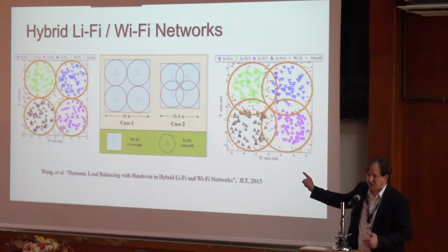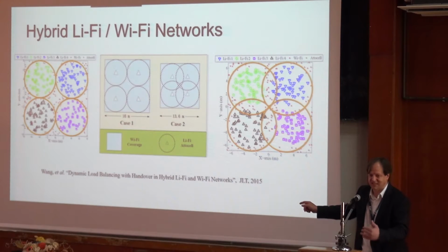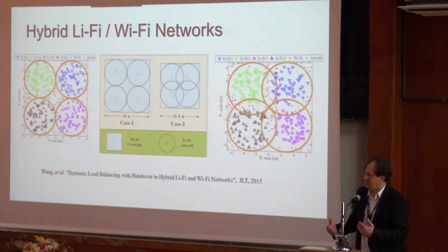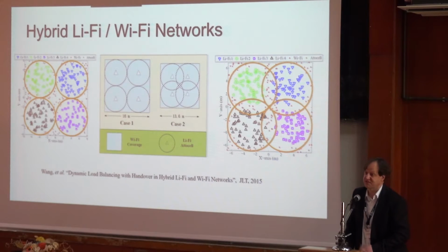We've then developed a simple load balancing algorithm that is based on the signal to interference plus noise ratio, SINR. Whenever the SINR of Wi-Fi is higher than the SINR of LiFi, the user will be served by Wi-Fi. That's why you see red dots in the interference regions. That means that users are covered by Wi-Fi.